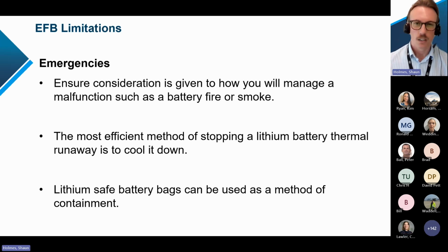What will I do if this device fails and starts to produce smoke or catches on fire? Okay, the likelihood is relatively low, but it is a consideration that we need to think about when we're using an EFB. So the best way to control that situation and stop a lithium battery thermal runaway is to cool it down.